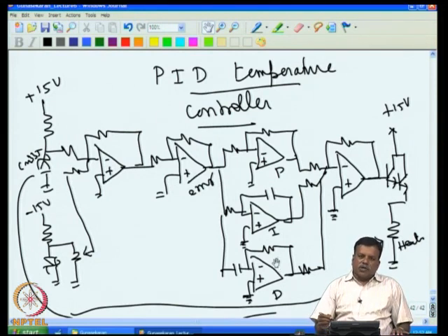That is good, because if I have only one time constant or only one delay in the system, then the maximum phase shift that you can get would be only 90 degrees, because one RC can produce only 90 degrees of phase shift, not more than that. With 90 degrees of phase shift, the system will not oscillate even if the gain is higher, and that is good for us because we don't want the system to oscillate. So it is always advantageous adding a differentiator, and that too if I match the differentiator to one of the time constants, one pole also gets cancelled, and oscillation of the system can be avoided.